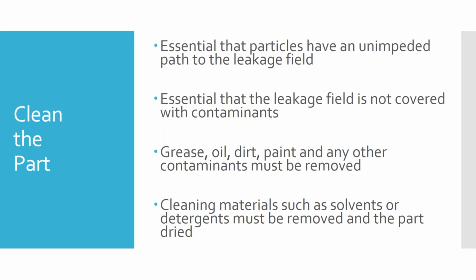You can't run electricity through a painted part, like paint is a resistor. And you would probably, if you do manage to get it to go, burn the paint in the process. And then the second is that the paint can be thick enough that the magnetic field won't jump up the surface of the paint and catch anything.